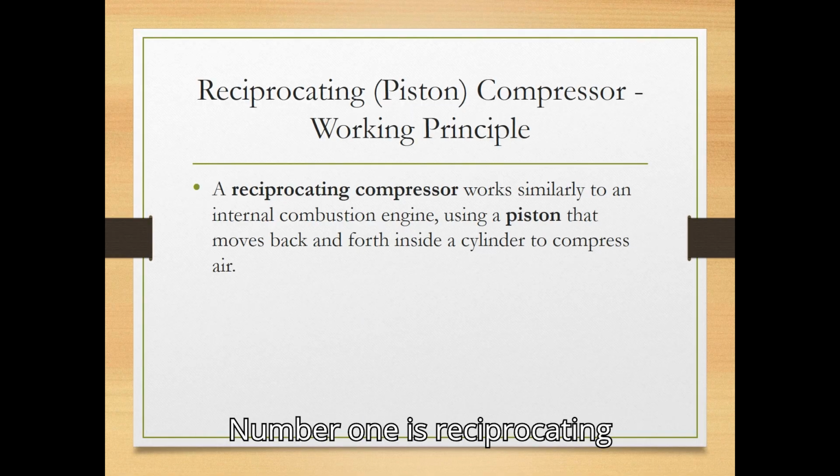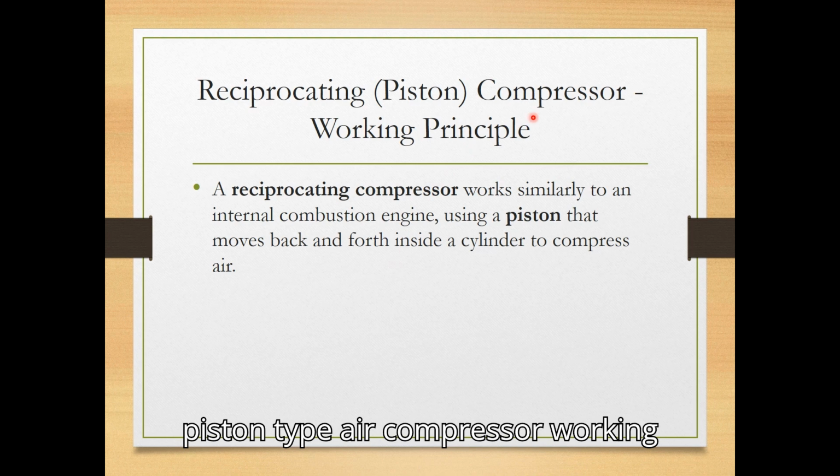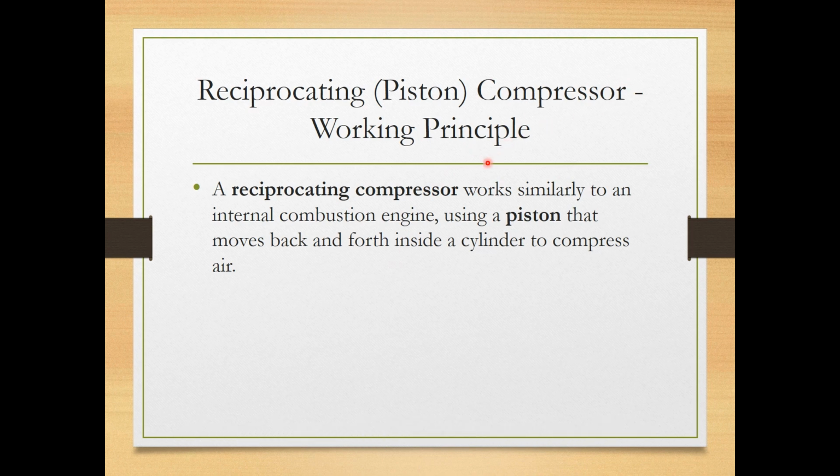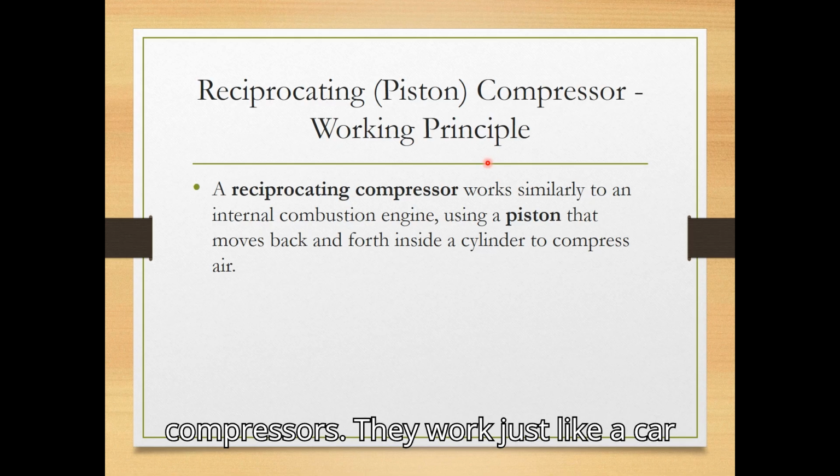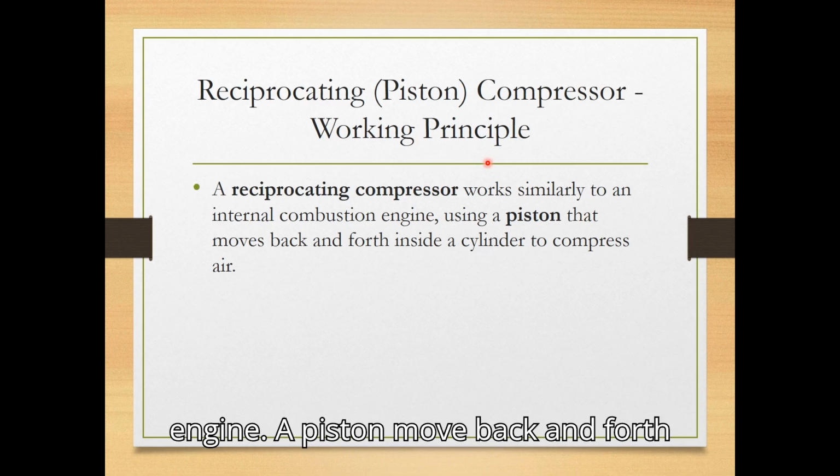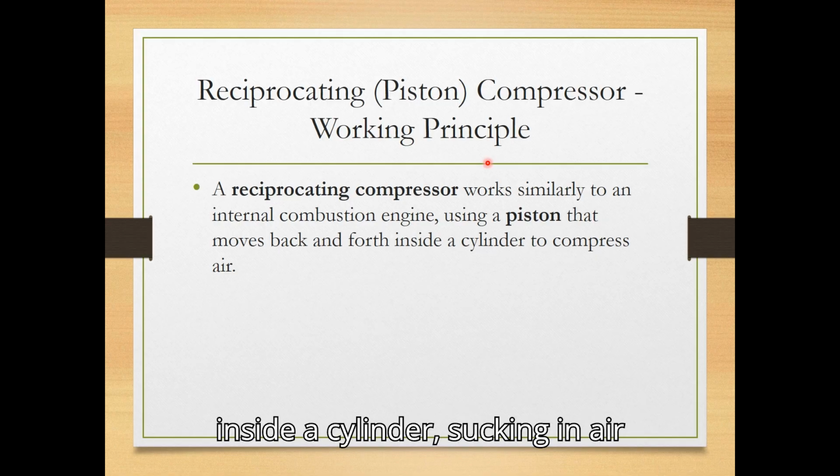Number one is the reciprocating piston type air compressor working principle. These are the oldest and most common compressors. They work just like a car engine. A piston moves back and forth inside a cylinder, sucking in air and then compressing it.